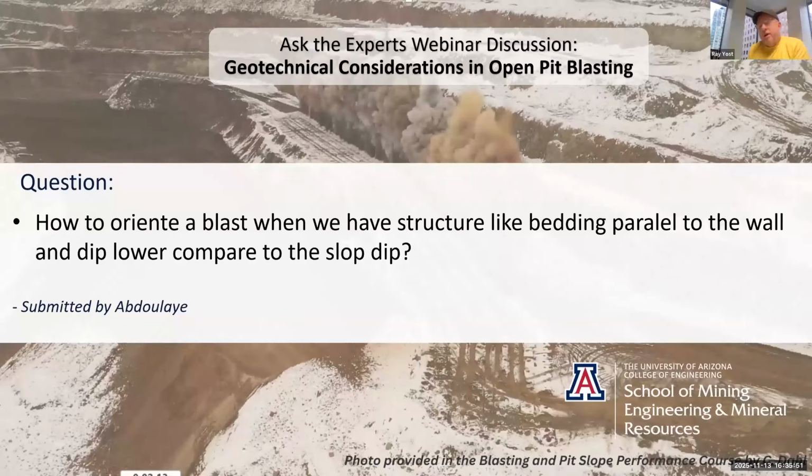Yeah, that's where you sort of get into that footwall mining. You're just going to bench down along the footwall and follow that bedding, and then step out every once in a while. Yep. But that's where design is really the answer to that. Yeah, or dip slope it if you can, and try and optimize it that way. Yeah, exactly.